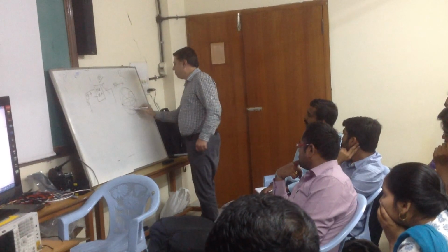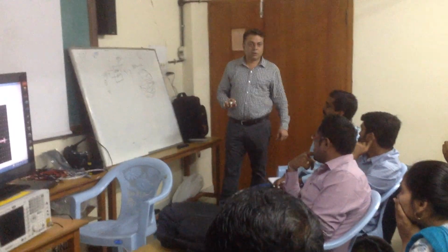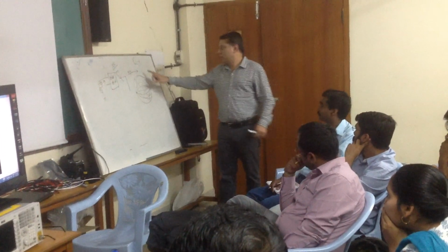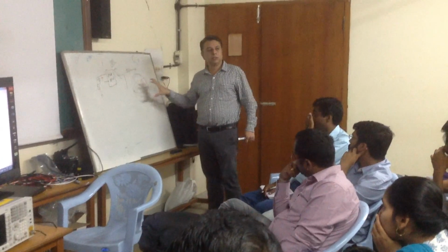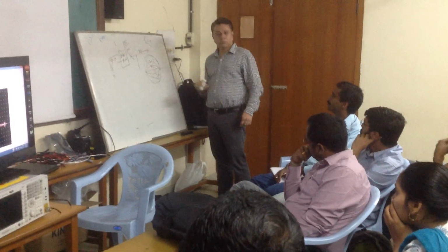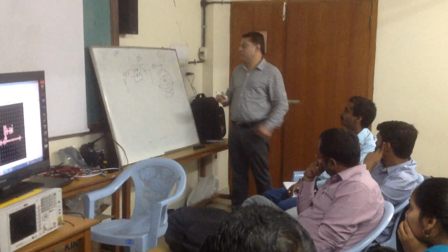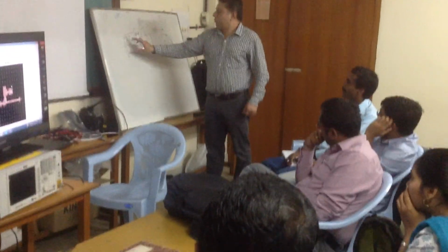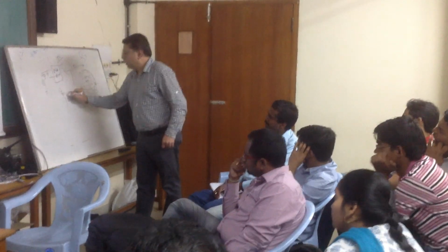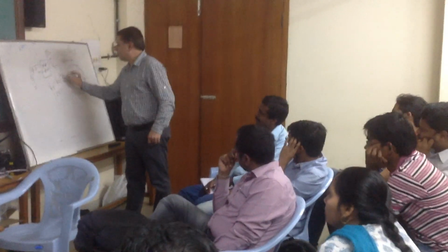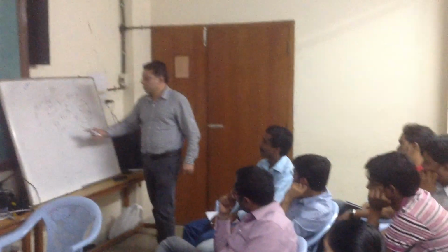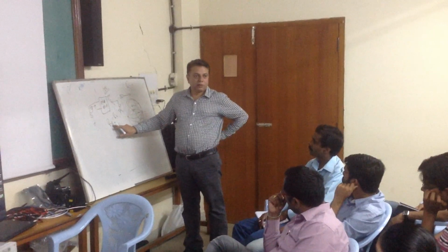This is in all the simulators you must have seen. You can keep the Q curves in drop mode, or you can bring the Q curves superimposed on the Smith chart, starting with Q1. This is one part of it. Now, once I have to go from 50 to 100, this is the relation you use. RP is the parallel resistance, which is always higher.